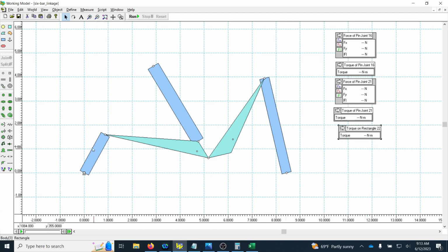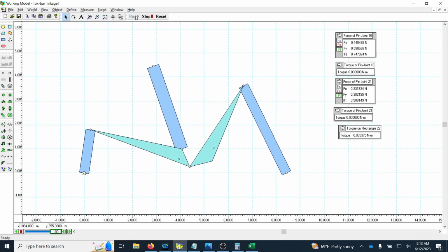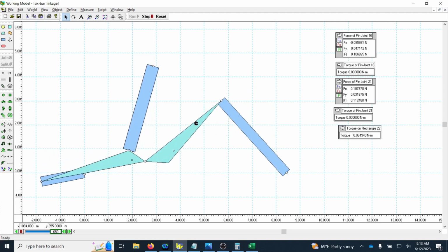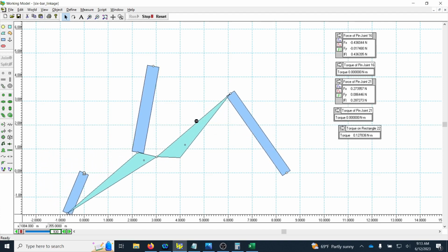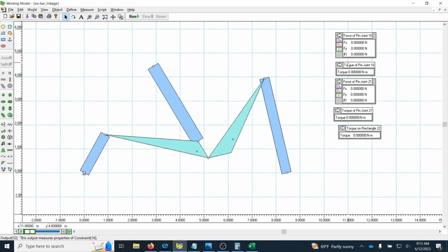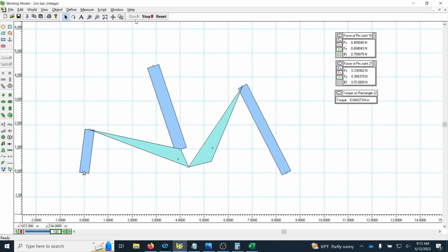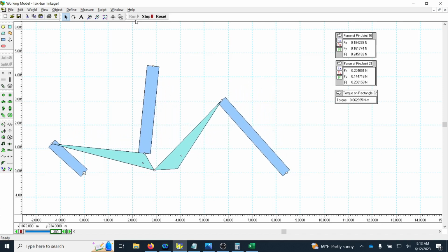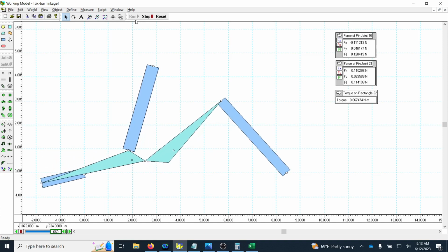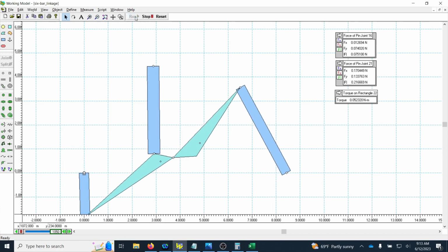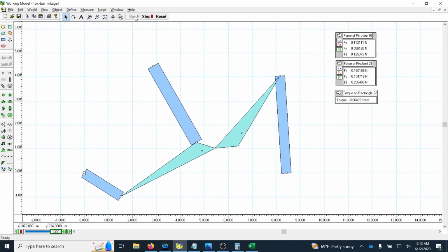And one suspicion I have is that because I have a velocity only here, it might not have any torque, but let's run it anyway. All right, so we can see a torque at the center of mass of the link that we selected. So with that, I'm going to reset, remove these 2 torques. So I'm getting 2 forces and a torque. And let's run again so that we can get all of that information, and then we can import to Excel and then do as we wish in terms of the dynamic analysis of the linkage.